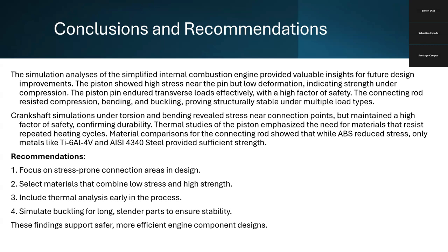Some recommendations that we would like to give. 1, focus on stress-prone connection areas in design. 2, select materials that combine low stress and high strength. 3, include thermal analysis early in the process. And 4, simulate buckling for long, slender parts to ensure stability. These findings support safer, more efficient engine component designs.